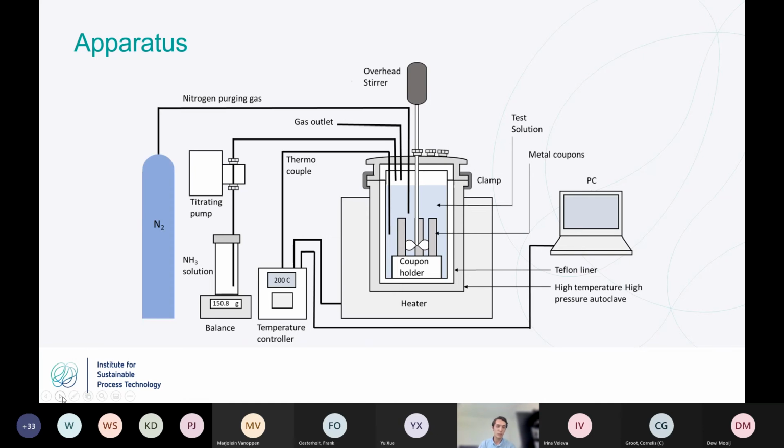Afterwards, these compounds or magnetite layers will be assessed with various analytical methods. Then they will be re-immersed into the autoclave again at a temperature of 150 degrees and with the mixer, which we can see in the middle, causing flow conditions, and with some acetic acid added to it to cause a pH of 6.